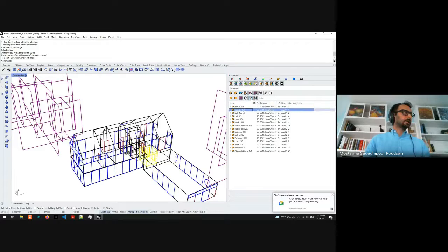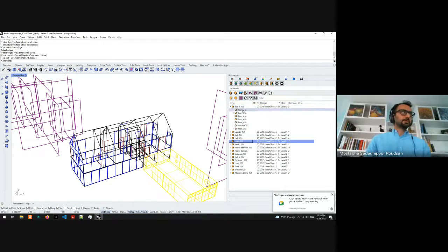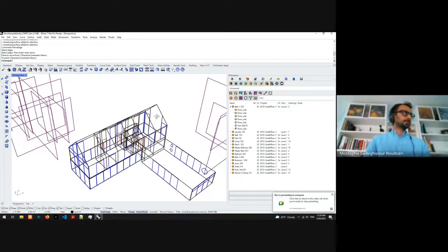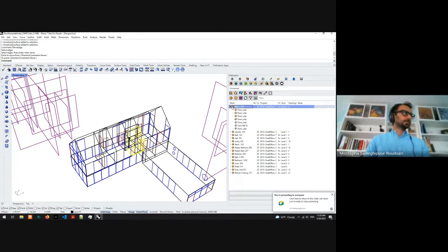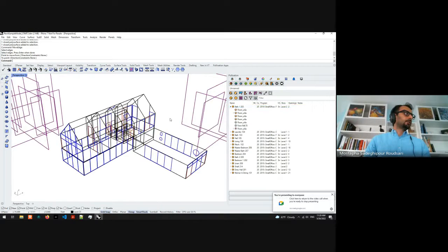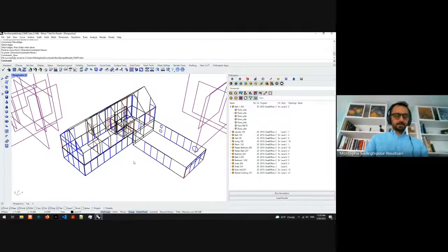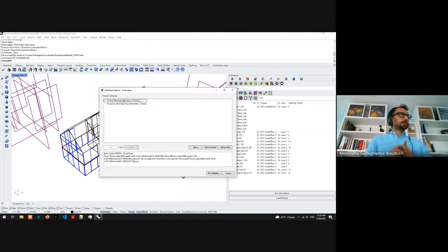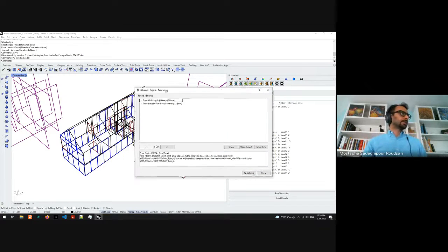Again, all these are simulatable zones, rooms, and I have access to all the faces and the program and everything. Now the next thing I'm going to do is validate the model. We have a command called PO validate model. What PO validate model does is it goes and checks for all the typical mistakes that we have seen people make during the last 9 years using Ladybug Tools, including ourselves. And we check for all of those.